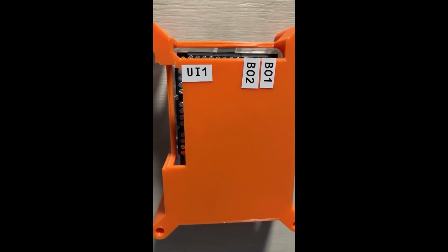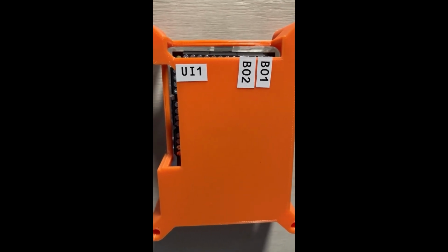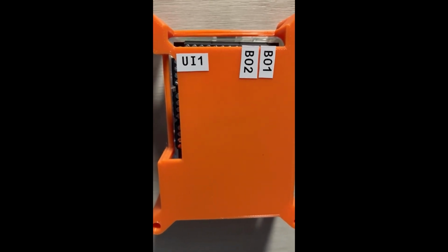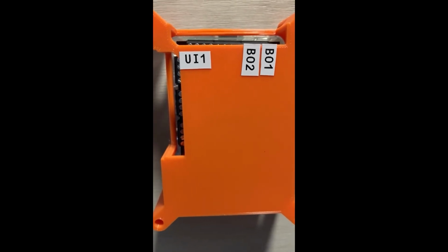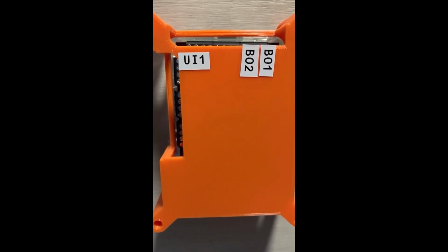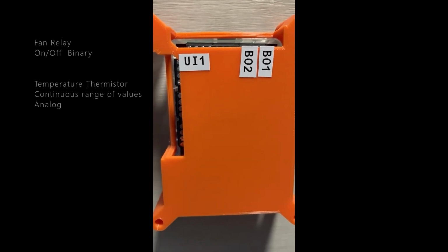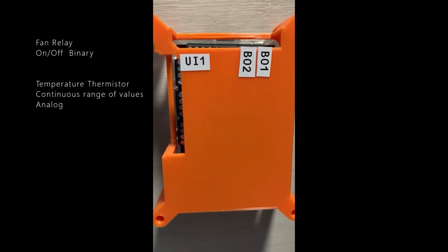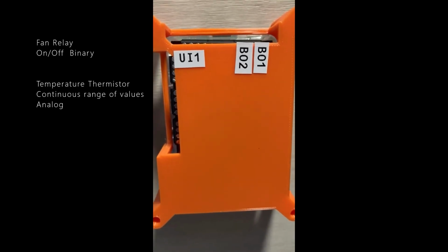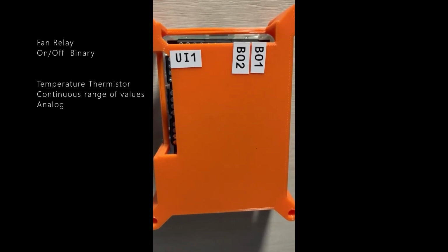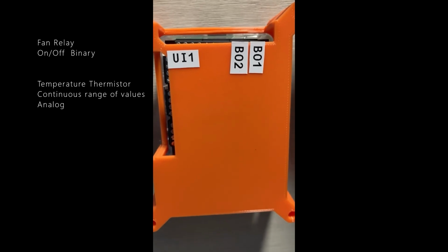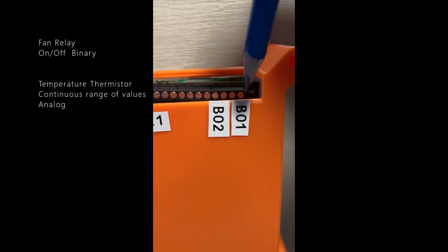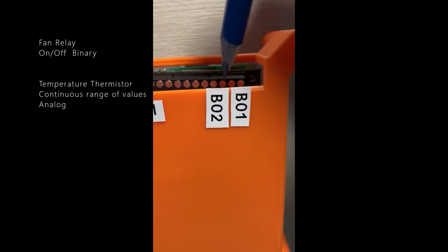We have a controller that I have not wired, so I can discuss a fundamental, important concept to know about automation signals. And that is, BAS communication signals are divided into two categories, binary or analog. The fan and light used in the building automation trainer is either on or running, or off, not running. Devices or signals that are either on or off are called binary. The light is wired to binary output 1, and the fan is wired to binary output 2.